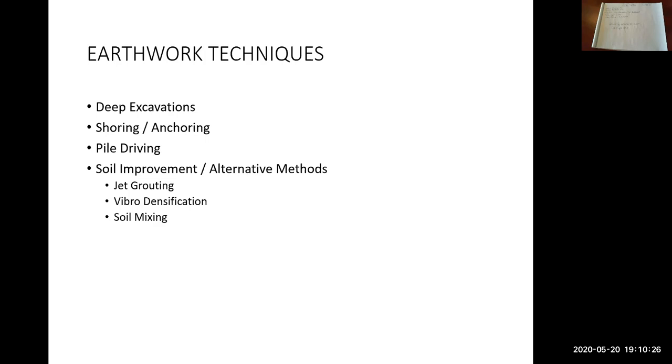So you can't slope the excavation. So if you think about a building footprint in downtown Vancouver, if it's a 10-meter deep excavation, if you tried to do a 1-to-1 excavation slope, your slopes would be way out into all the surrounding roads.